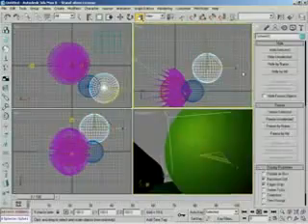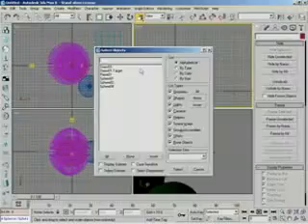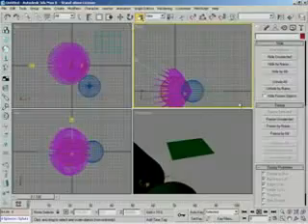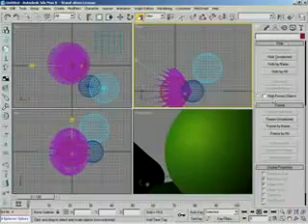If I want to take this guy right here and I want to hide this selected object, simple enough. If I want to go in there with a select by name, find that particular object, select it, and then say hide unselected or unhide all or unhide by name, I have the ability to start coupling these things that you've seen together. I can also just come in here with an unhide by name, grab, unhide it like such. So this just deals with hiding and unhiding, which is going to be really important based on things like the speed of your video card. Maybe if you have a really complex scene, you need to get things out of your way. Maybe you don't want to see things like joints if you're working on a character. The list goes on and on.